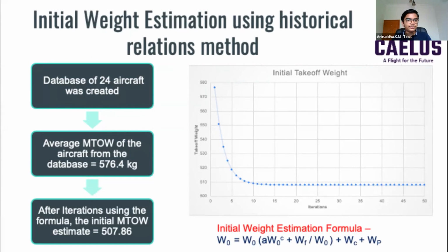For conceptual design, we only use initial weight estimation. The other weight estimation methods, the detailed weight estimation, we use in the preliminary and detailed design stages. By iterating this formula repeatedly, we have found the final maximum takeoff weight as 507.86 kilograms.